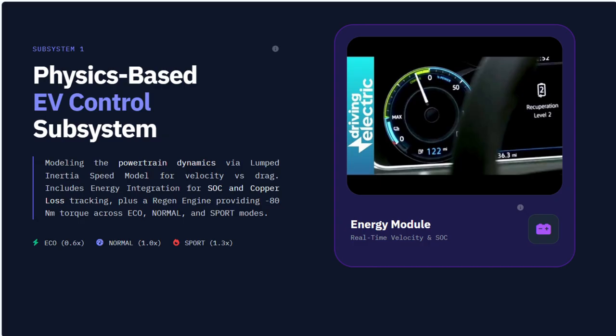into the firmware. First, I implemented the lumped inertial speed model. Using numerical integration, the ECU calculates the true linear velocity every 10 milliseconds by balancing the commanded motor torque against the aerodynamic drag and rolling resistance variables. Second, the energy model computes the real-time battery state of charge, or SoC, by tracking mechanical work